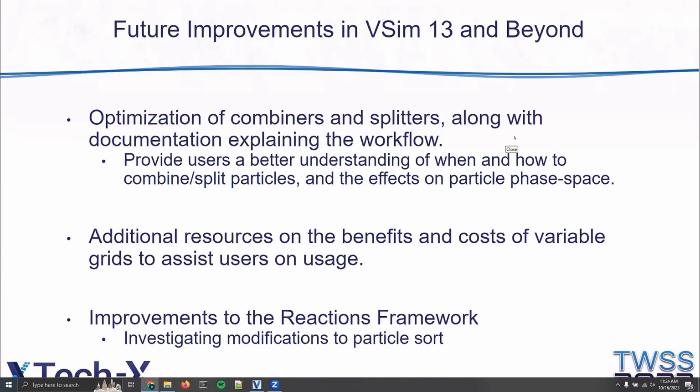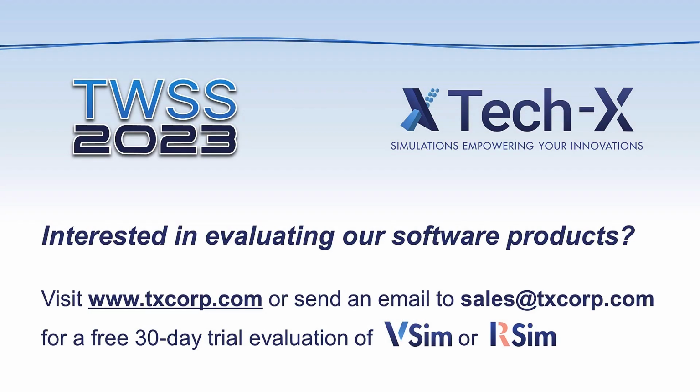Why not use cylindrical domains to better capture particles? In the case of our Penning 3D example, the geometry itself would not lend itself to a cylindrical domain. That can certainly be applied to a number of other simulations or geometries. Really, our main thought was to work on how we can better improve the usage of computational resources that are already available to an end user. And this particular path also had the widest ranging effects in that any user in any physical regime can use this domain decomposition workflow, regardless of whether or not they're in 3D Cartesian versus 2D cylindrical or 3D cylindrical.